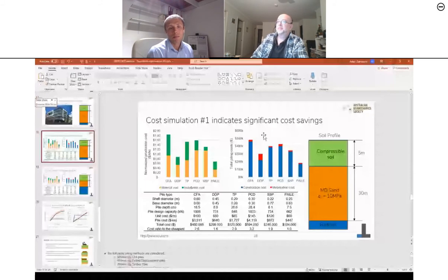The formulas are dependent on the CPT cone resistances typically, and that's what drives the design. So I'm not sure if there is any such requirement. Yes, the rate of expansion will definitely have impact on how the pressures within the soil dissipate, how quickly. But ultimately, that should not be a driving factor.